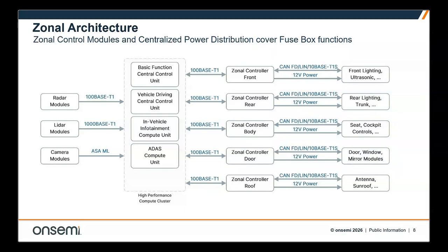Here in this slide, we see the big picture of what zonal architecture looks like in practice. As you can see, zonal control modules replace the traditional central fuse boxes entirely. Each zone in the vehicle gets its own intelligent module that handles local power distribution, diagnostics, and load management, right next to the load it serves.